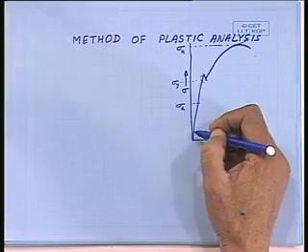And we limit our working stress to something known as allowable stress by taking a factor of safety onto the material stress, where we take sigma y to be the maximum, and therefore sigma y by some allowance, which we say is the factor of safety, gives you sigma a.